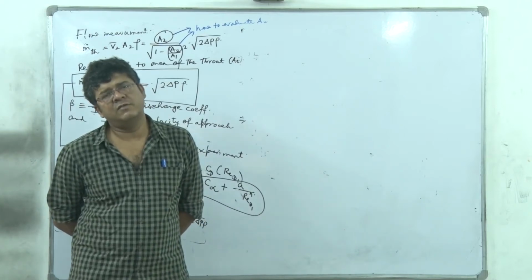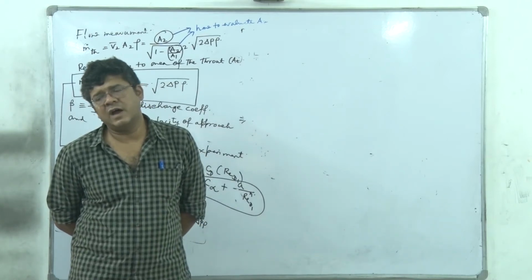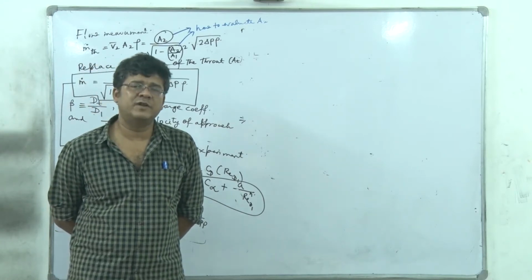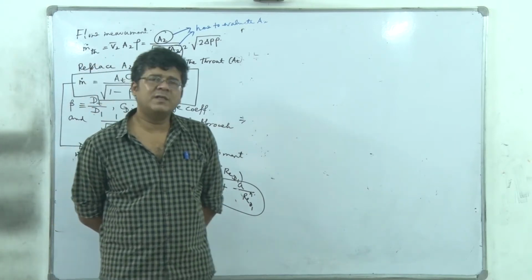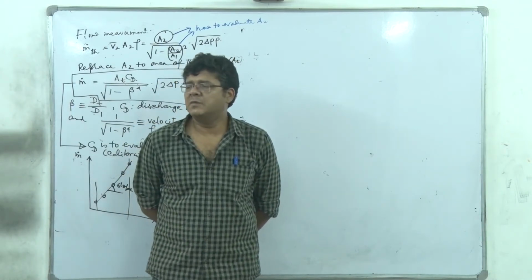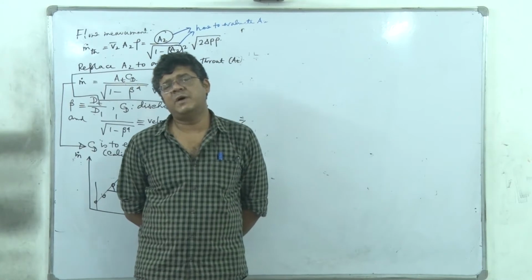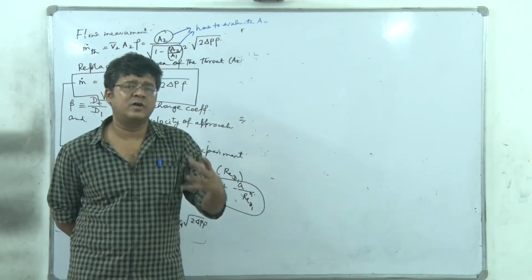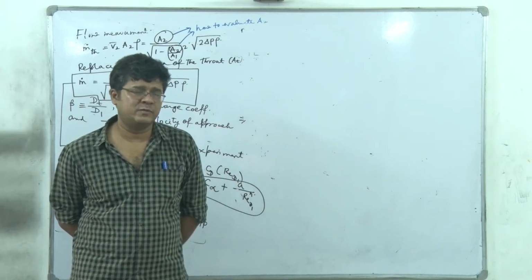However, in the far downstream the pressure is not at all equal to the pressure in the upstream. There is a permanent pressure loss, right? P1, and if the far downstream point we consider as 3, then P1 minus P3 is a permanent pressure drop, whereas P1 minus P2 is a temporary pressure drop, and that we are measuring for flow measurement.